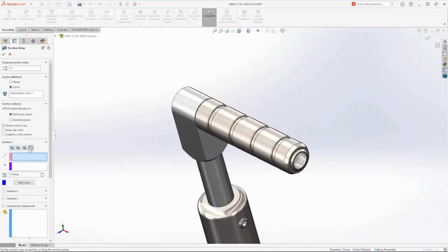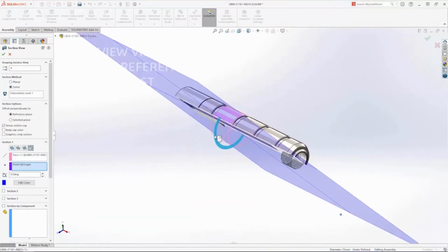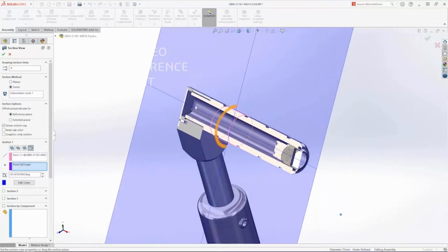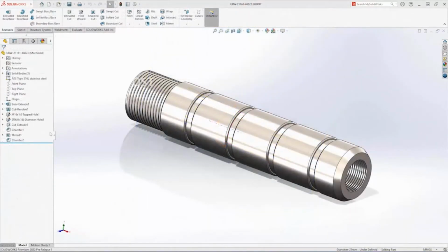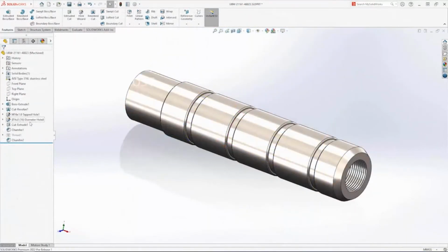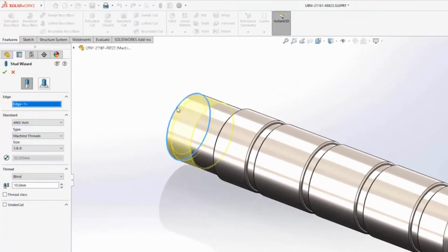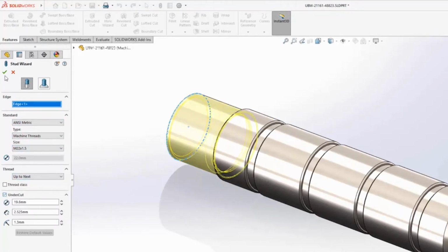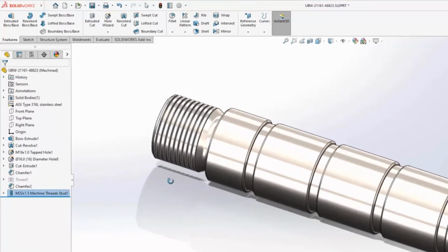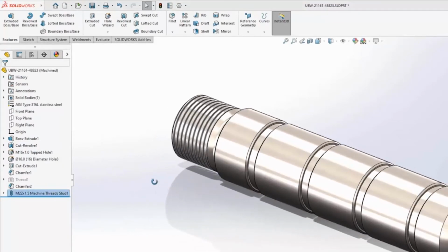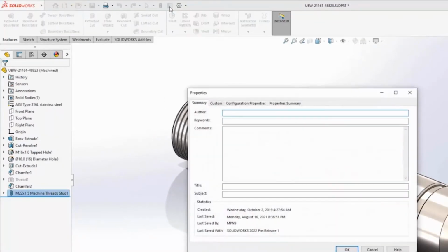These 22mm cut threads are useful for rapid prototyping, but it's too much detail for higher volume manufacturing and they make the file complex. The new Stud Wizard is a great choice here, as it automatically recognizes the diameter of the boss but still provides a list of different thread sizes and pitches to use. You can even create an undercut with full control over the dimensions. The Stud Wizard adds cosmetic threads that can be called out in a 3D annotation or 2D drawing.